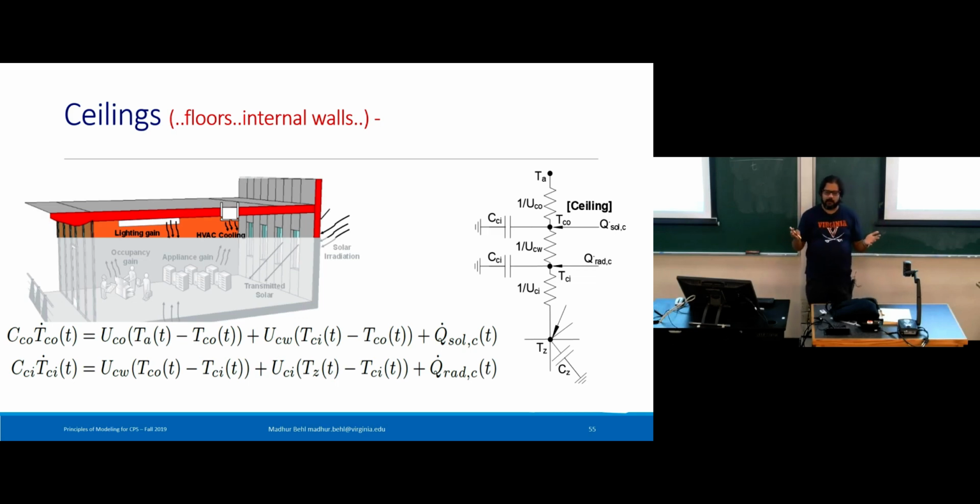So for an internal wall, you can actually do many things. You'll see an example of this shortly. Like in this room, we have 3 internal walls if we treat the ceiling as its separate branch. So you have the choice of having 3 different 3R2C models, one for each wall. But if you think about it, and that applies to this room, the outside is just a corridor. And the wall to my left and the wall at the back of this room are connected to the same corridor, correct? So there is a reason to assume that the boundary condition would be just the average corridor temperature.